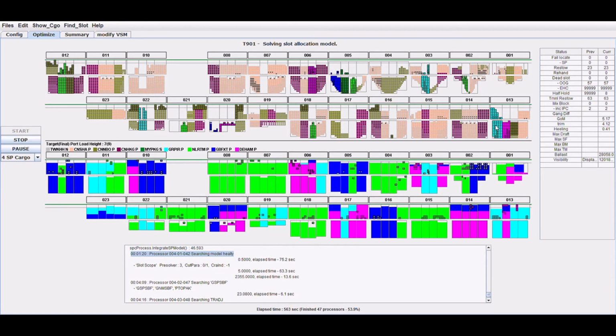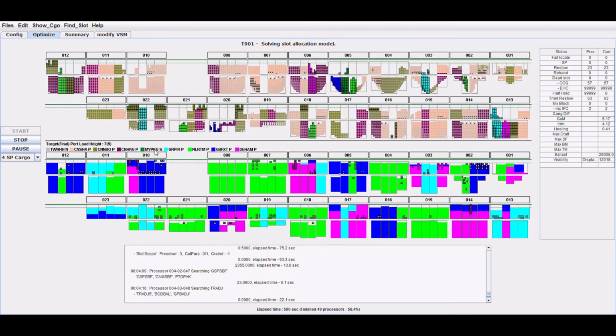This optimization process is repeated for all ports from Kaohsiung, the first port on the route, to Port Kelang, the last port. In addition to the evaluation factors considered in optimizing the block stowage pattern, several factors are considered in the slot allocation process: minimizing void space due to high cubic or OOG containers, and locating the container position considering weight distribution within the block.